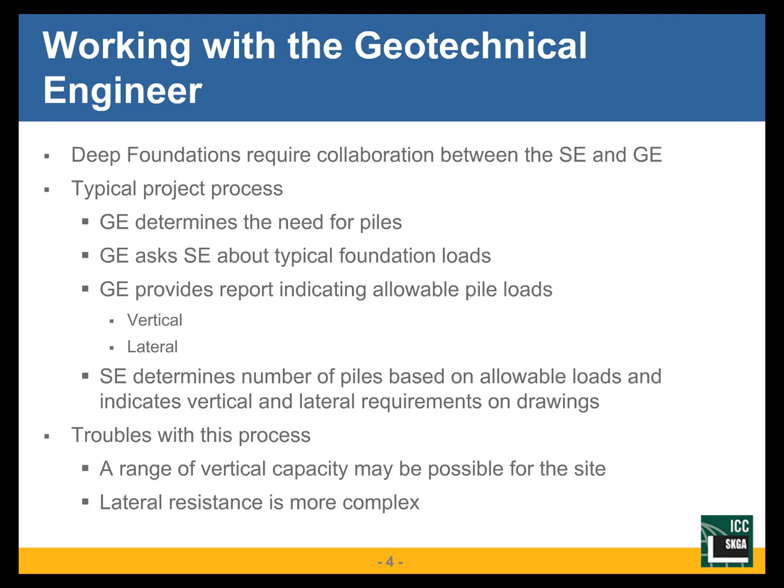The problem with this process, which is pretty much a straight handoff process and not a collaborative process, is that a lot of times there's a range of possible vertical capacities for a given site. At any given site, you may be able to use significantly higher or lower capacities depending on how deep you put the piles.